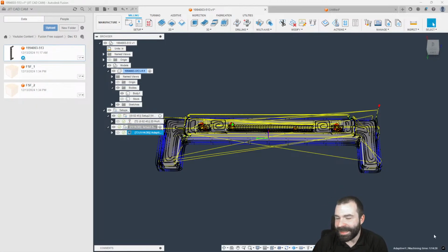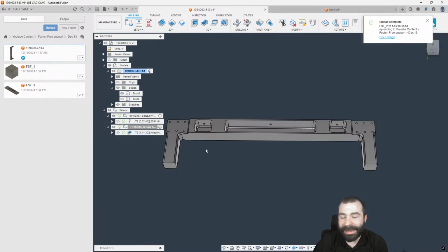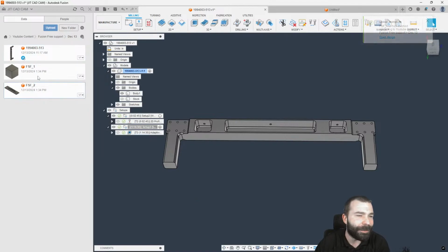100%, Ryan. It's a neat trick. Another way that I've seen a couple of shops do it is if you have an old Bridgeport mill and you want to rough machine something there, that works out really well too. Using a router to cut blanks. I've seen it any and every way possible.